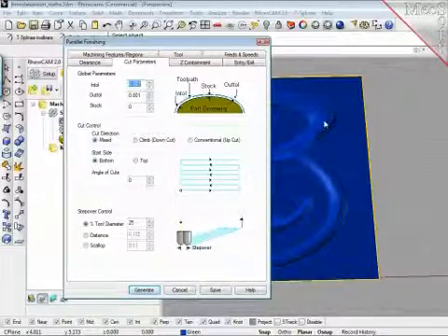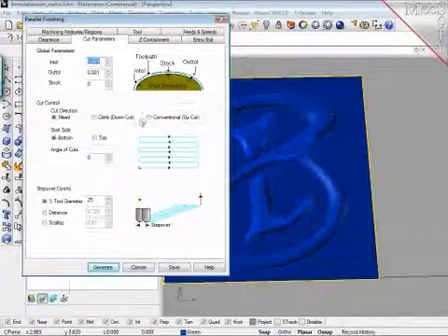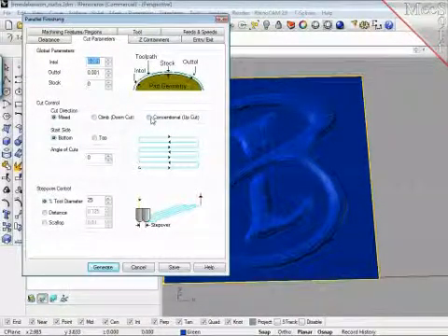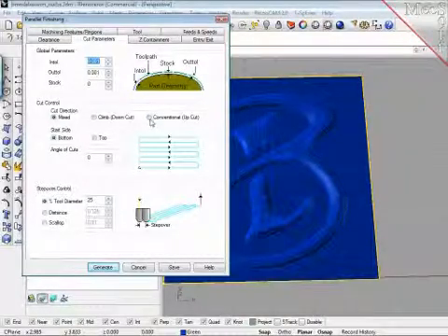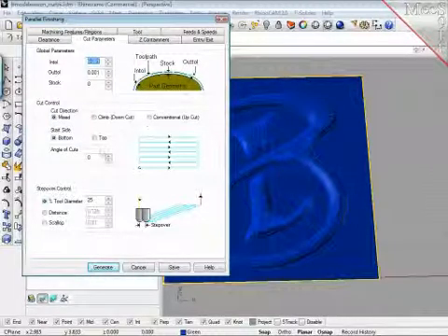Sometimes there are reasons for roughing or for finishing not to be too accurate or to be very, very accurate. Then cut direction is a very interesting point. The cutting tool only rotates in one direction, and here you can control which way the cutting tool is presented to the material, only in one direction all the time, or mixed in both directions, backwards and forwards.